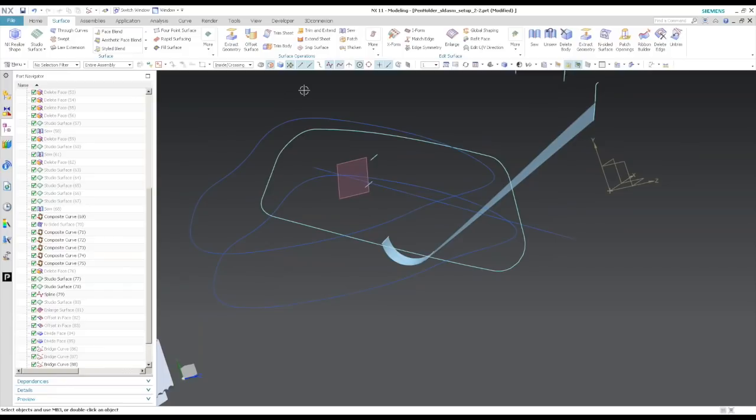I just find, and everybody I know that does multi-axis finds, having the ability to quickly create reference curves and surfaces just helps create a cleaner toolpath, higher quality surfaces, faster machine times. And so having the ability right in the same system as your CAM to quickly create those without having to go to another application, create them, export, import, and go back and forth. Here it's just apply, application, modeling, application, manufacturing. You instantly get feedback as far as what the results are, and I just find it's a lot quicker.